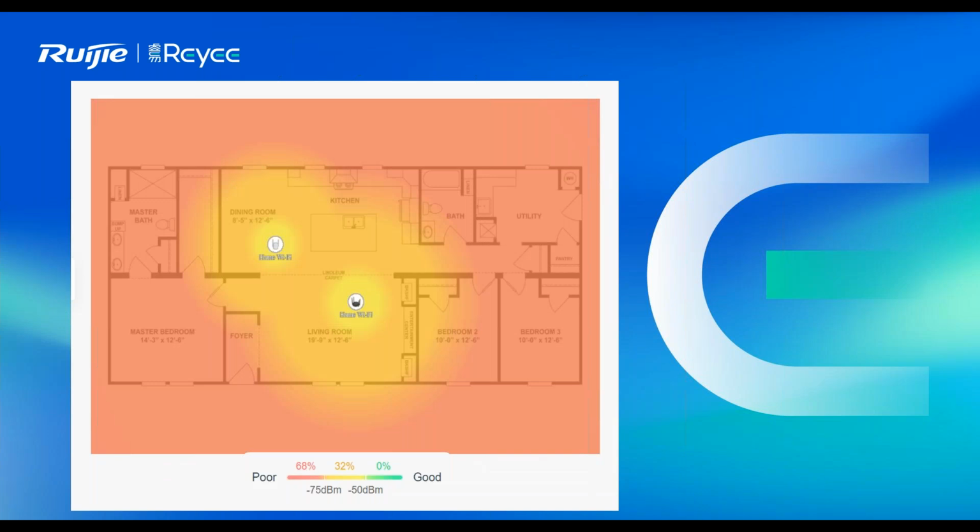And if we can see here in the next floor plan, we're installing just a home Wi-Fi access point or router, and we have a home Wi-Fi range extender. This kind of setup based on these two devices is insufficient for this area. If you just see in there, we have a living room, a master bedroom, master bath, dining room, kitchen, usually what we have at home. This is not going to work really well because the signal is not the best, right? The heat map should be in green in order to provide full coverage to the entire home.